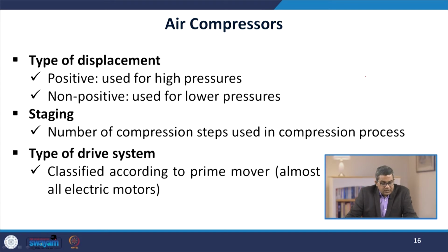Apart from this, the type of displacement also contributes towards the classification scheme. It may be positive, that is used for very high pressure, and non-positive, that is used for lower pressure. And above all, staging, that is the number of compression steps used in the compression process, may be 2 stage, 3 stage, 4 stage, and so on.